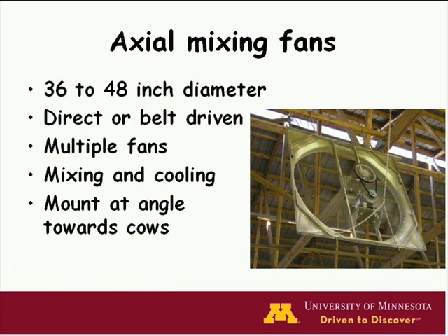The throw is usually 10 times the diameter in feet, so 30 feet is how far apart with a 3-foot diameter fan. 40 feet apart with 4-foot diameter fans is typical. And they can be combined with some sprinkling watering system to provide some extra cooling, and then they do the mixing. Key thing is to mount them so that they blow down towards the cows.